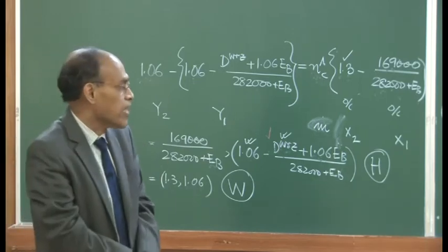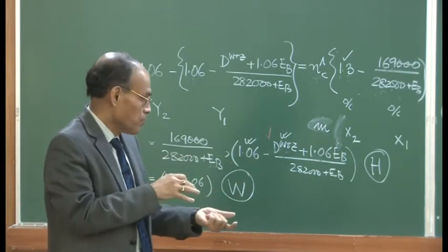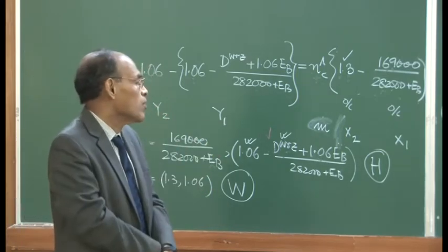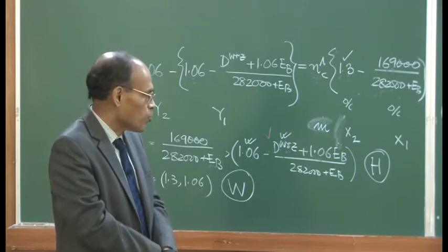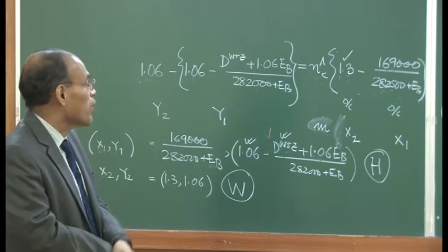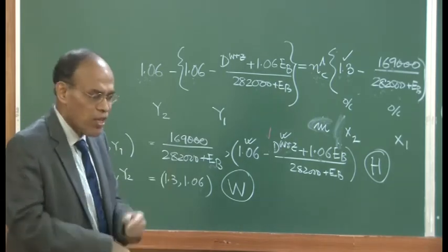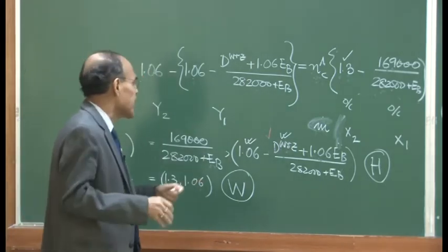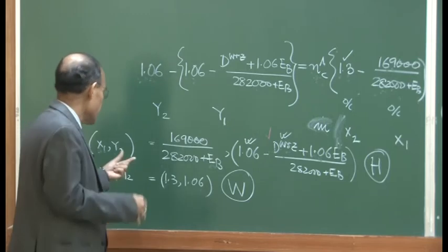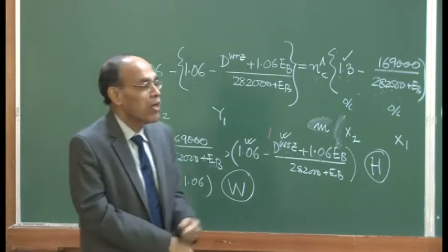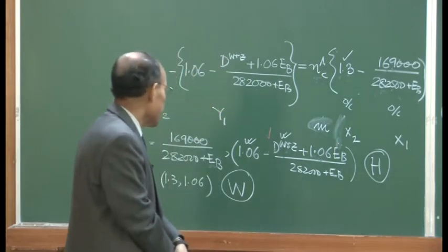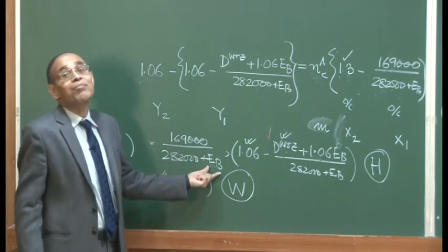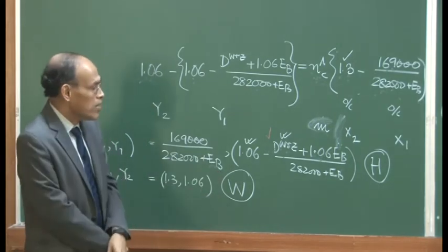It's a heat exchanger, and when it is on gas, the stove is heated up. When it is on blast, the stove gives up its heat to the blast, and therefore this transport of heat, which depends on the residence time, which depends on the surface area, there are certain constructional problems that we cannot really go beyond 1200-1300 degrees centigrade through the standard stove that we use and the kind of bricks that we apply in those stoves. So there is a limitation of the equipment, but theoretically speaking, I would say higher the blast temperature, more efficient is the blast furnace operation.